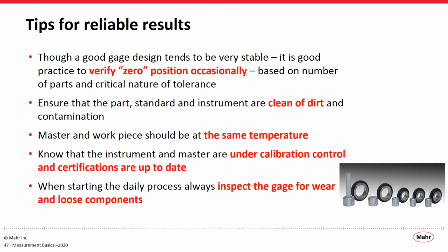Make sure that the master and the workpiece and the part are all as close to the same temperature as possible. As you know, different materials expand at different rates because of temperature. Trying to keep those as close as possible. And also make sure that your masters and instruments are under calibration controls and certifications are up to date.